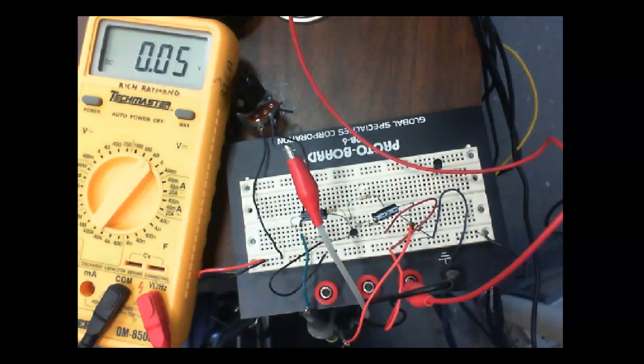Close. And by the way, guys, this is your main tool for troubleshooting these transistor amplifiers, is understanding this bias. If the bias is wrong, then it's going to identify what problem we have. So I can measure this bias, and I could almost guarantee that we can figure out where the problem is just by measuring the bias.